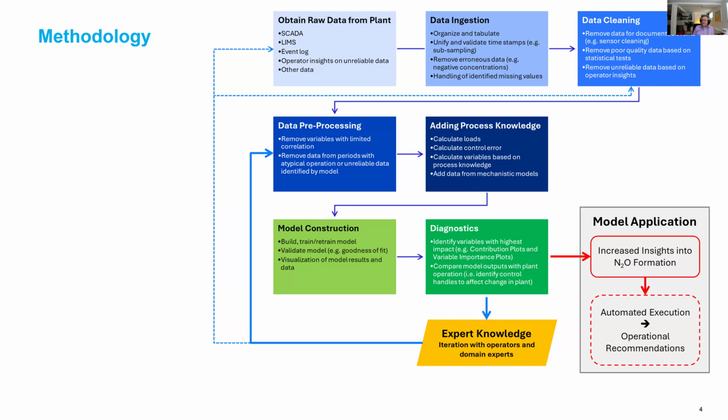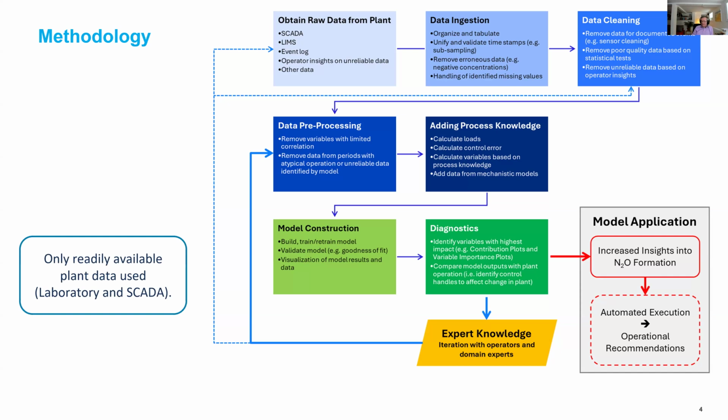And if you have a reliable model, then you can start using the diagnostics to increase your insights into what is driving N2O formation. A step further, which is clearly not the focus of this project, is to find ways to mitigate N2O emissions. And again, except for the two N2O sensors, there was no additional measuring campaign. That was all standard data available at the plants from the lab and from the SCADA system, right? So nothing on top. I'm not saying you shouldn't do that, but we had very limited time and budget, and we had to use what was already available.